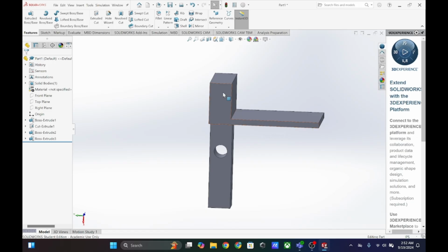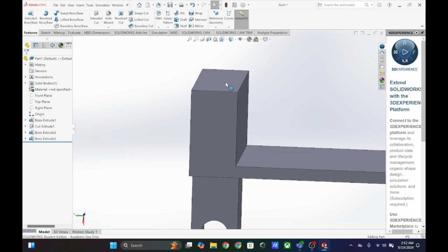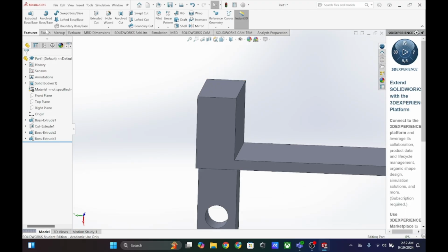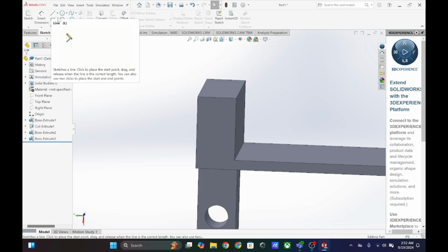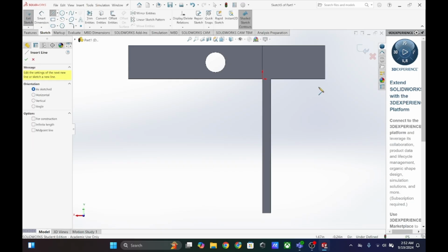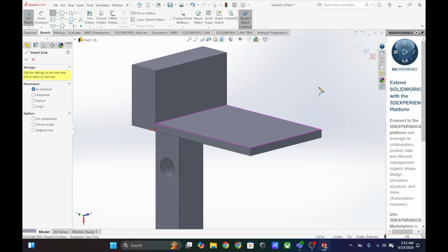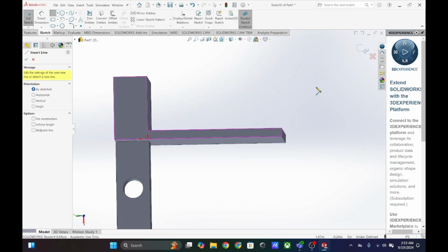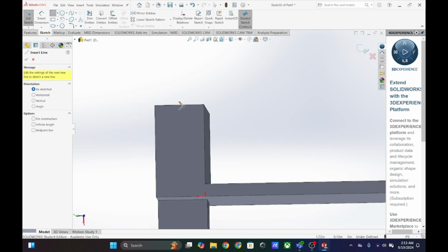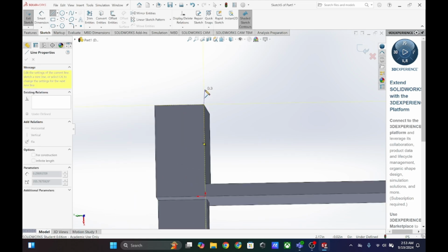Now we are going to extend off the top exactly how we will hold the magnifying lenses as well as the viewing lens. We're going to use a feature that we have not touched yet in these sketch tools. So starting off with just a normal line, we're going to select this side surface. I am going to change the orientation just so that it is easier to view. So starting at this sketch surface, we're going to select this corner and go up by 1 inch.